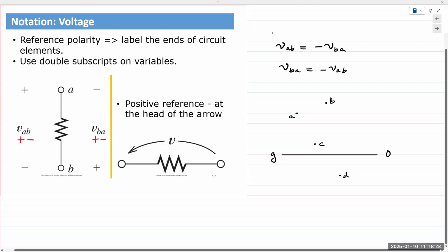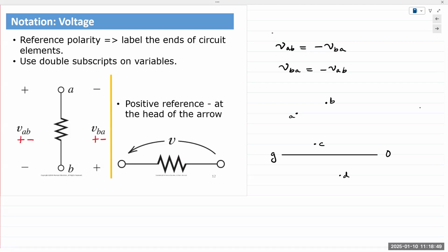Ground actually doesn't mean anything in this case. In our circuit, if you see a ground symbol, which is something like 3 horizontal lines in the shape of a triangle, it notes the reference point in a circuit. Because if your circuit is running on a battery, like a DC battery cell, it's not physically connected to the earth. It's not physically connected to ground. Right? So let's say you have these 4 points in a circuit, A, B, C, D, and then G. So let's say 5 points.